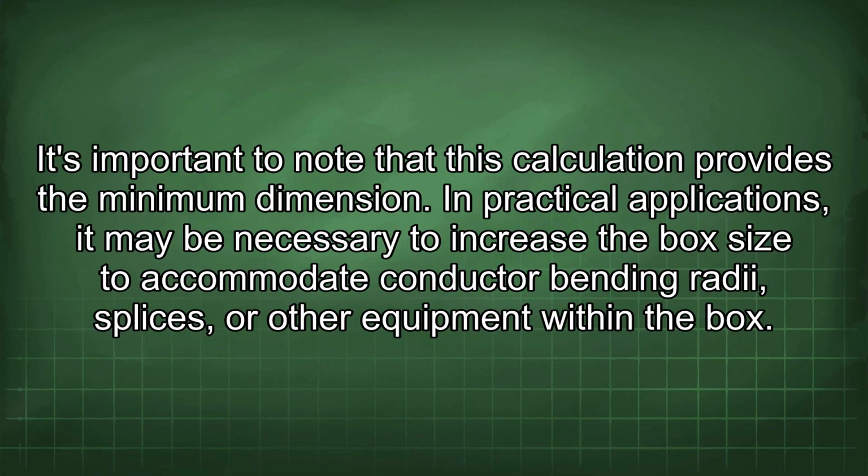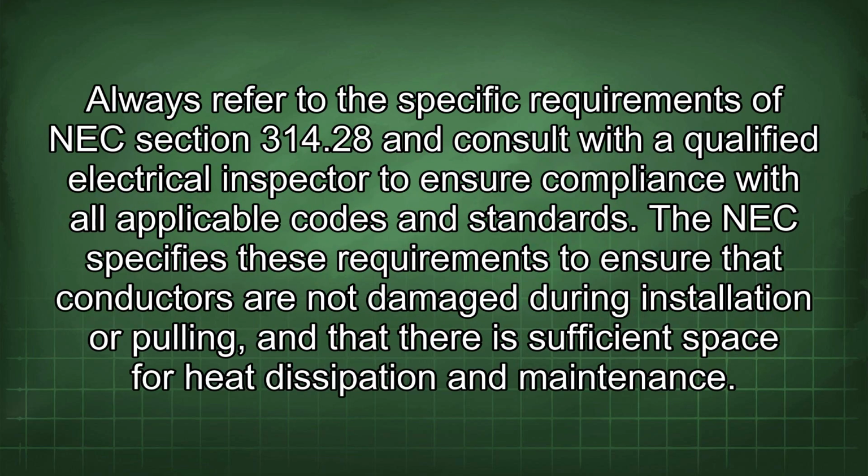It's important to note that this calculation provides the minimum dimension. In practical applications, it may be necessary to increase the box size to accommodate conductor bending radii, splices, or other equipment within the box. Always refer to the specific requirements of NEC Section 314.28 and consult with a qualified electrical inspector to ensure compliance with all applicable codes and standards.